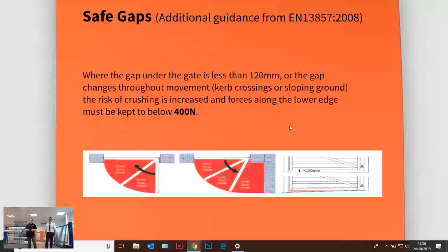So it's a greater risk, and we're generally looking to use safety edges, or laser curtains will get fitted to it. And the laser sensors actually move with the gate. On the swing gate, you have one on the inside on the top corner by the hinge point, and one on the outside in exactly the same position, and they move with the gates.